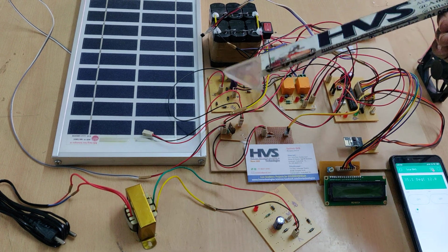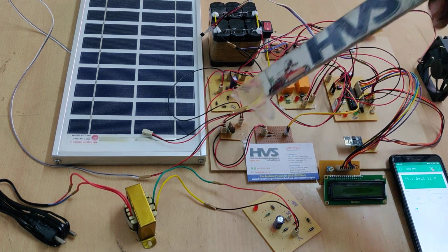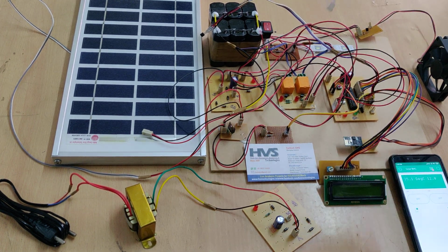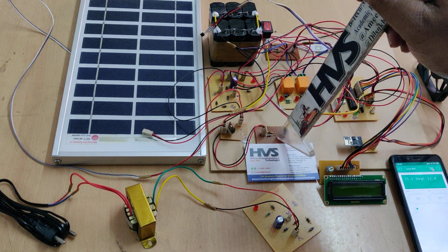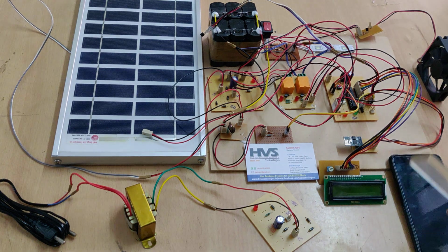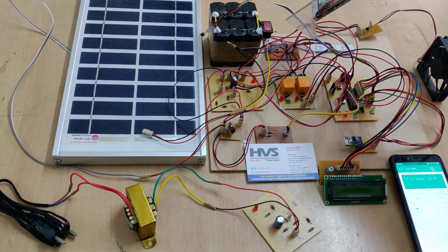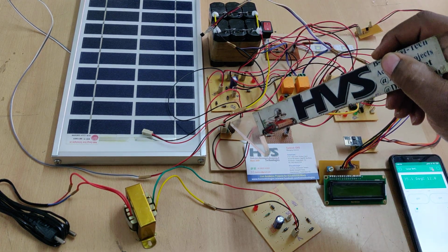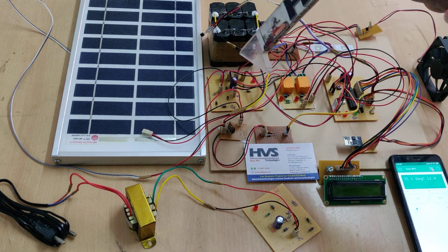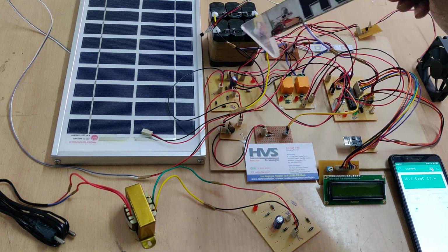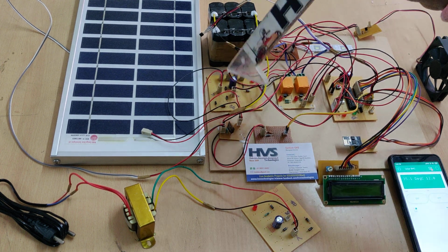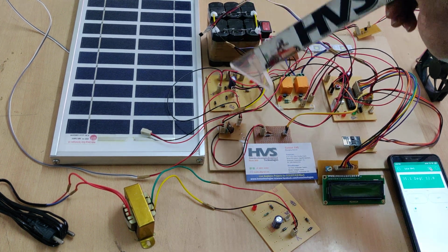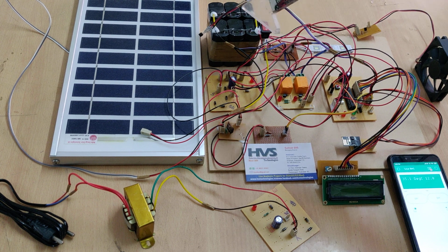In parallel we will get maximum power. That will be controlled by our PIC microcontroller by continuously measuring the solar panel voltage along with current from this sensor. And also we are measuring the battery voltage. After this MPPT circuit, the voltage is given to this rectifier circuit. If there is any reverse connection or reverse polarity, the rectifier circuit will rectify that and provide the same voltage to the battery.